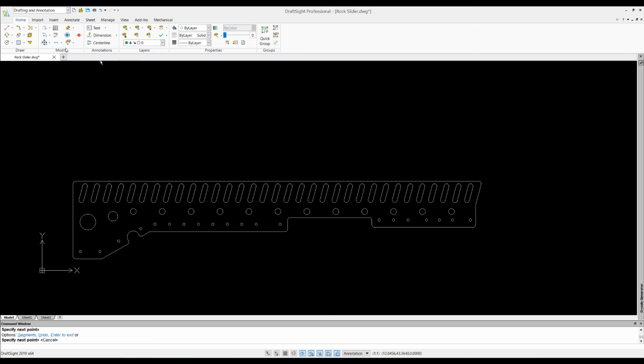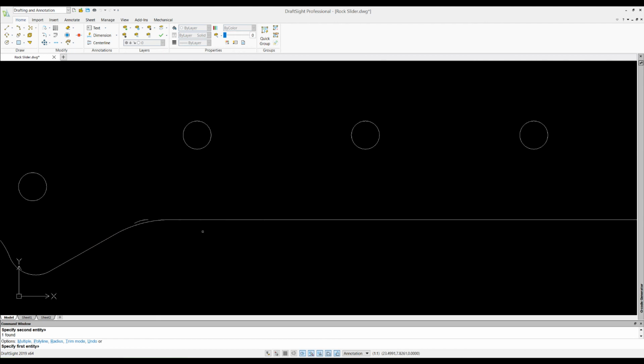Okay, so now the only thing I don't like about it, I wish this was a little bit bigger, so let's do a new fillet, and let's do multiple inner, the radius inner, and change the radius. I want to make that kind of big. Let's try 2 and see what it looks like. There, so let's select these 2. Yeah, that looks pretty nice.